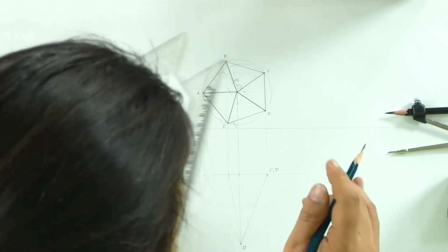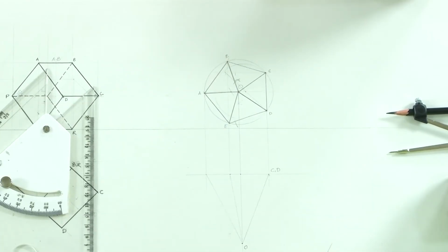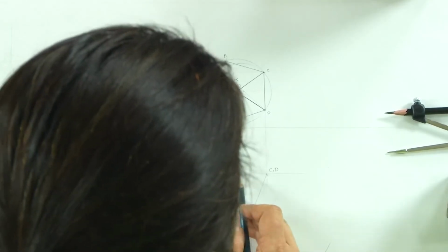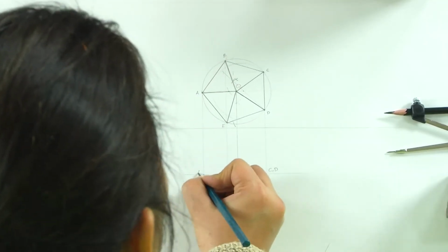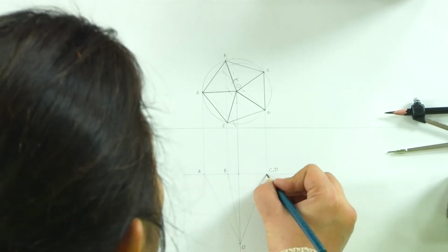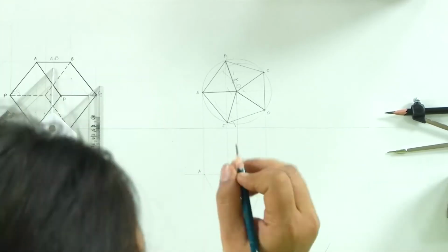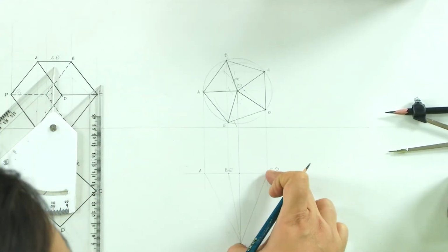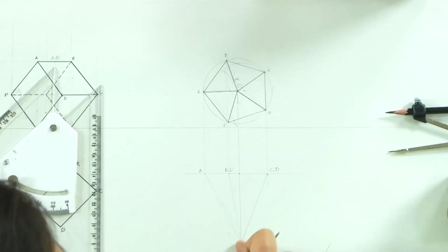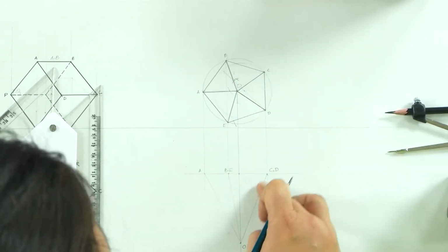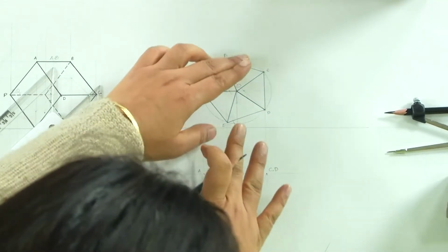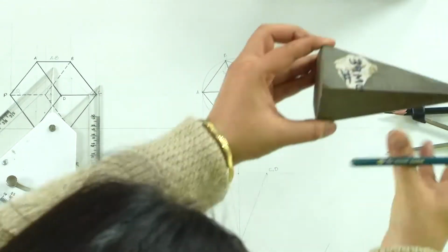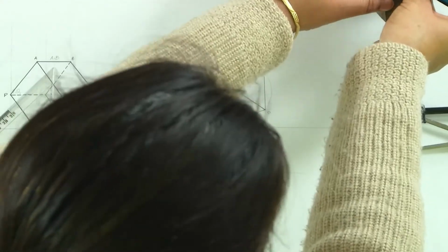This is the top projection. Now what happens, and I will also simultaneously make this axis here. So we have A, B, C, D and E beneath it. Now what we are doing is, we are making this side, which is represented by this line which is connecting CO and DO, we are rotating this entire figure in such a manner that this face is now parallel to VP.